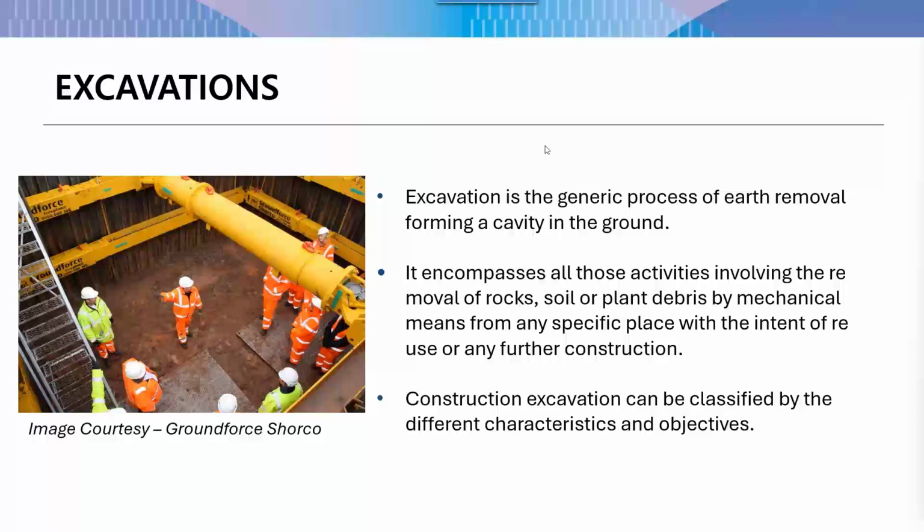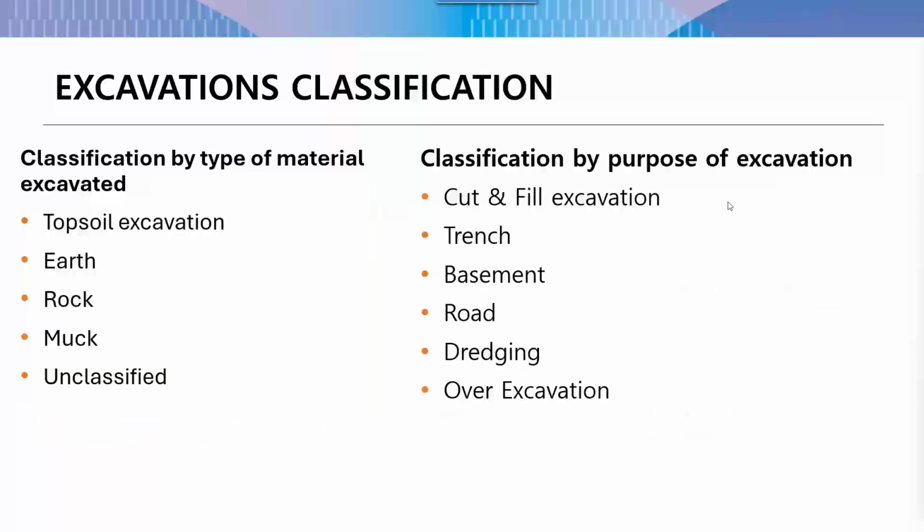Excavation can be classified based on different characteristics, basically the type of material or the objective of the excavation. On a broad scale, it can be classified into two types. First, by type of material excavated: topsoil excavation, also called topsoil stripping; then earth excavation, which can go deep; then rock excavation, either the outcrop of a hill or where the top surface is rock; or muck excavation.